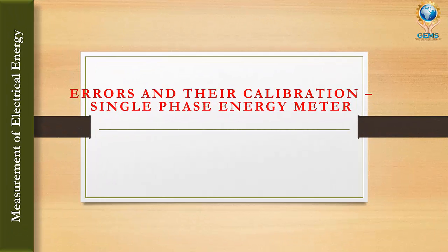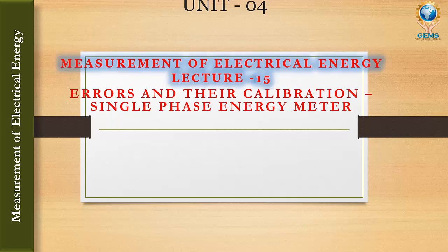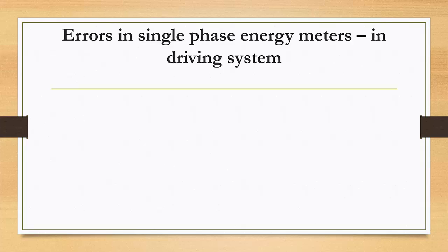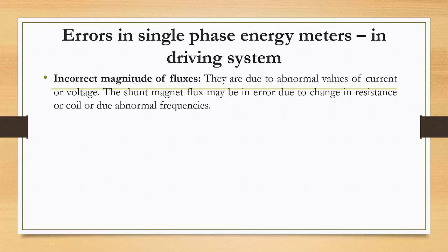Hello everyone, welcome to the video lecture on errors and the calibration in a single phase energy meter system. In today's video lecture, we will see what are the possible errors in a single phase energy meter and especially in the driving system. So the first error is incorrect magnitude of flux.